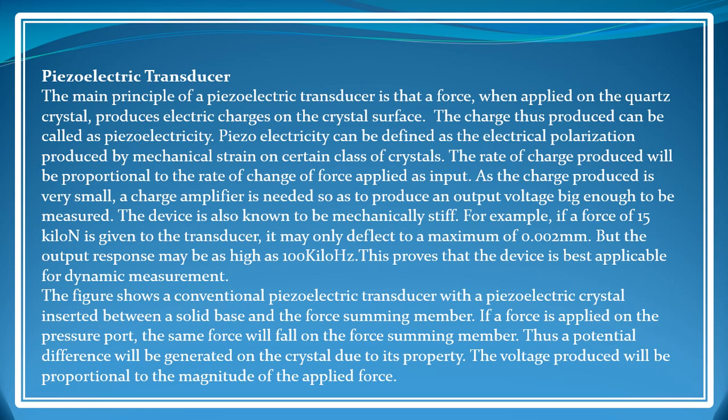The device is also known to be mechanically stiff. For example, if a force of 15 kilonewton is given to the transducer, it may only deflect to a maximum of 0.002 mm, but the output response may be as high as 100 kilohertz.